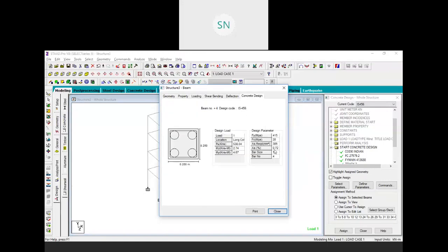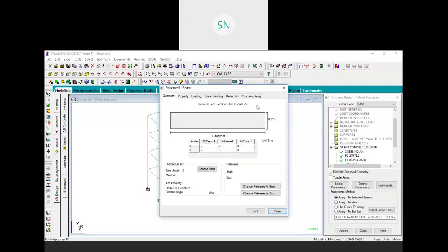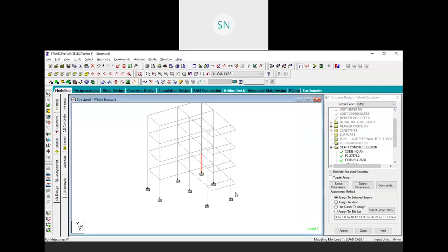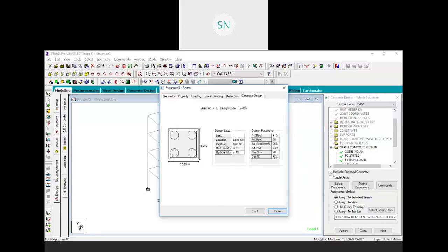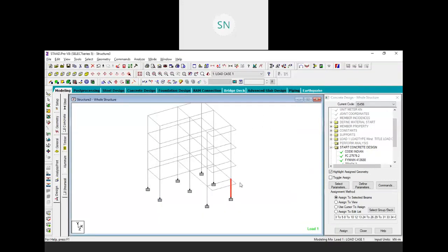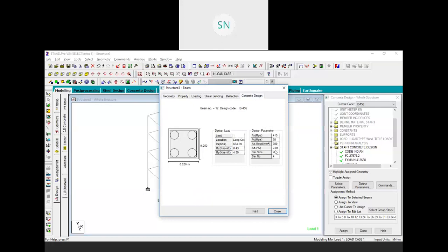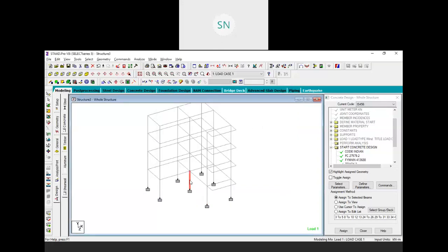Similarly, you have to check all your ground floor columns. So we have 0.72% steel. Here we have 2% steel. See, 20 mm, 4 members. And on this, again we have 2% steel. So these three columns carry much load, and the percentage of steel is higher compared to my requirement. My requirement is below 1.5% and above 0.5%, right? That is my requirement. So we need to increase the size of these three columns.